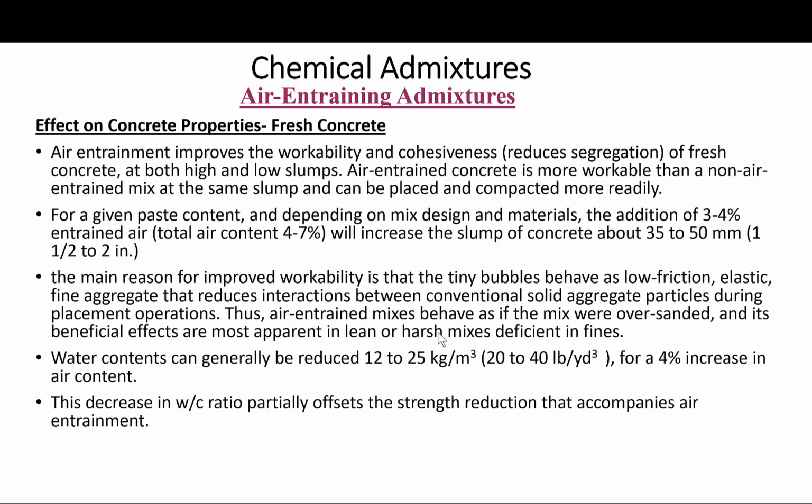Air entrained concrete is more workable than a non-air entrained mix at the same slump. Keeping the same slump, air entrained concrete is more workable and can be placed and compacted more readily than non-air entrained concrete.